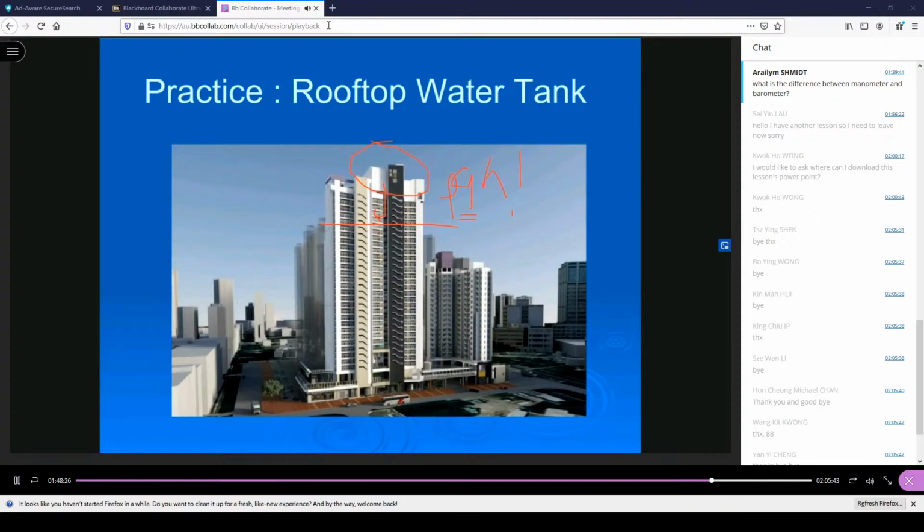Sprinkler water. Sprinkler is smaller, fresh water. Now you are not going to the rooftop, of course. But on every building there should be a water reservoir on the top of the building, to maintain a steady water supply at the upper part of the building. For the lower part, maybe a pump. On the upper part, you have a big reservoir, and remember, rho gh, the hydrostatic phenomenon, helps you to get water supply from the reservoir.